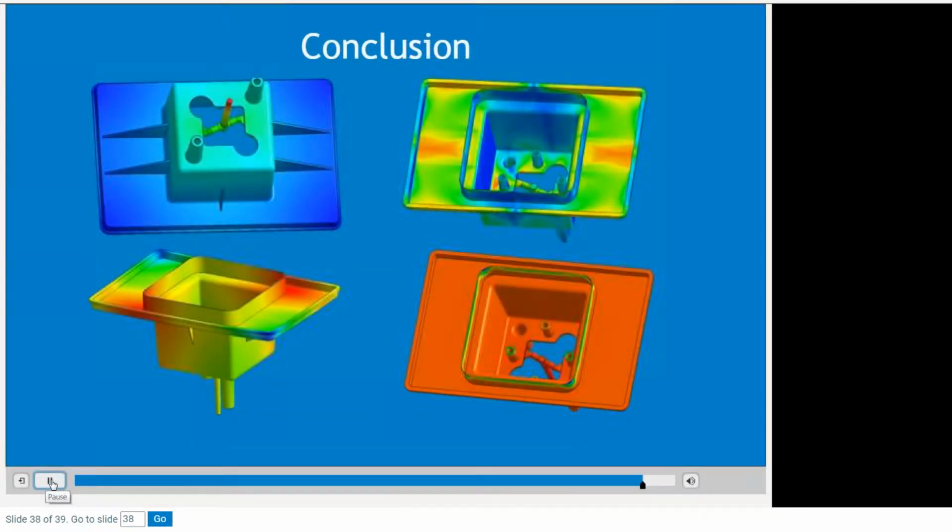Designing and molding high-quality parts starts with optimizing part design and gate setup. Symmetrical gate placement and gate sizing has a significant impact on molded part properties and flatness. Once a part design is optimized and proper gating is determined, the mold design can be optimized, resulting in a less challenging processing step. By checking off each of these steps in the injection molding workflow, successfully molding high-quality parts can be achieved.